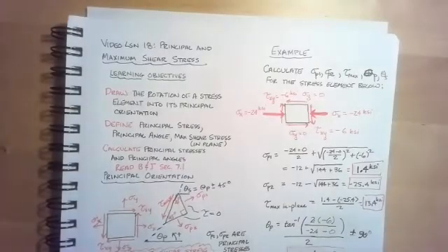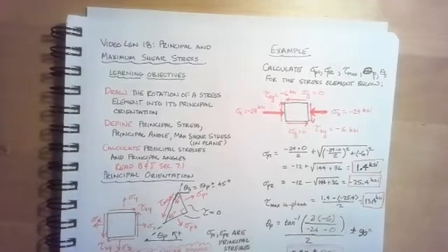Hello, and welcome to video lesson 18 on principal and maximum shear stresses. Our learning objectives for this lesson are for you to be able to draw the rotation of a stress element into its principal orientation. You should be able to define principal stress, principal angle, and maximum in-plane shear stress. And you should be able to calculate principal stresses and principal angles for a plane stress element in any orientation.